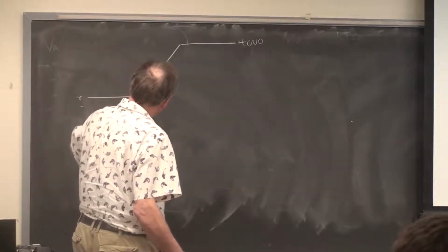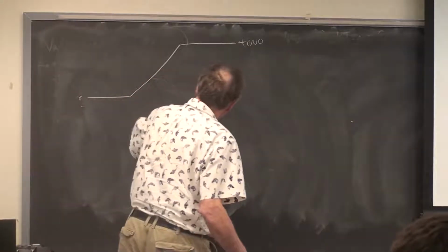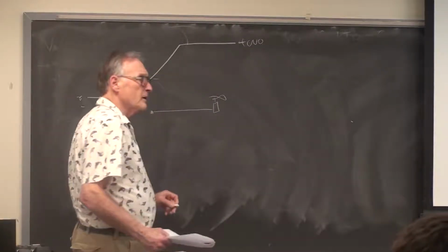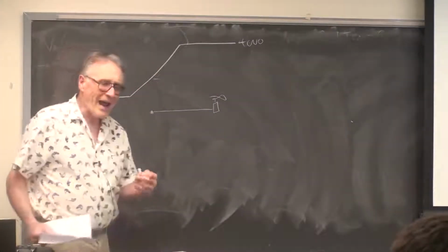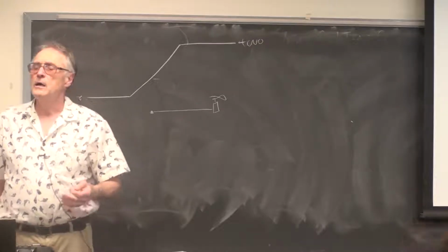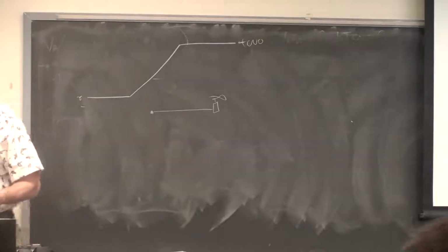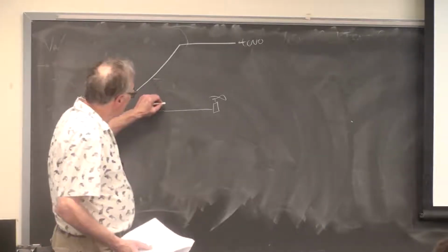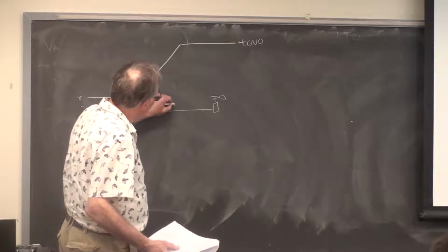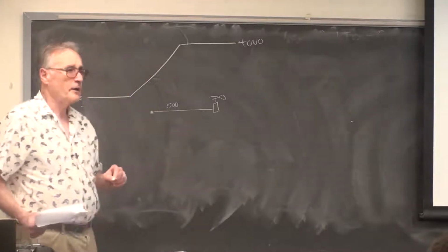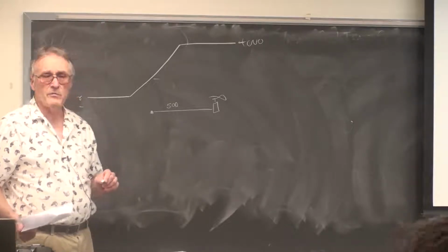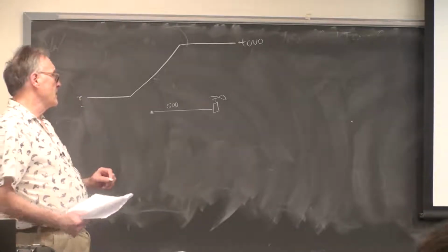And the potentiometer, when held with the beam horizontally, should be set to about half of the maximum ADC value. The maximum ADC value is 1023, 10 bits. So we'll say that when this is horizontal, the angle is 500 ADC units. It's about half the range of the ADC.